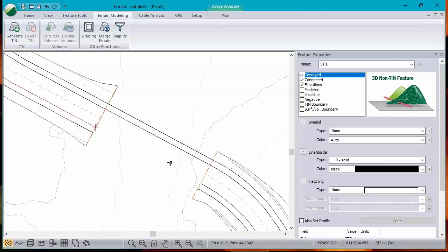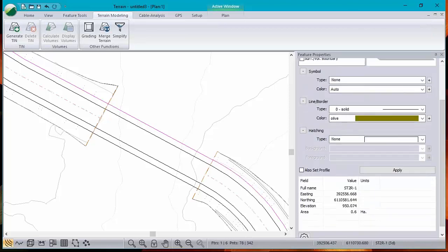So I'm just click, shift click, Control J join. Click to select, shift click to select another one, Control J join. Okay, so these have well-defined elevations. And they are where the bridge would go. I could have exported the bridge features as well, but I didn't. So this is just kind of a quick shortcut.